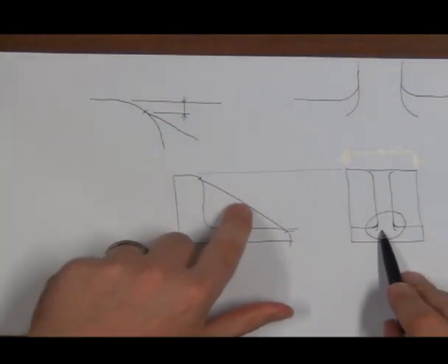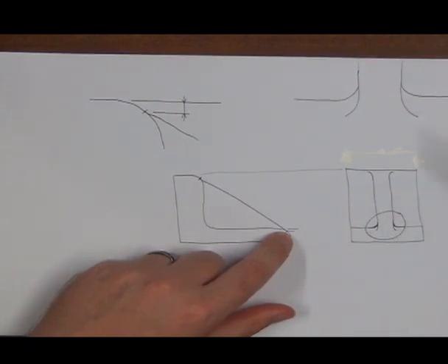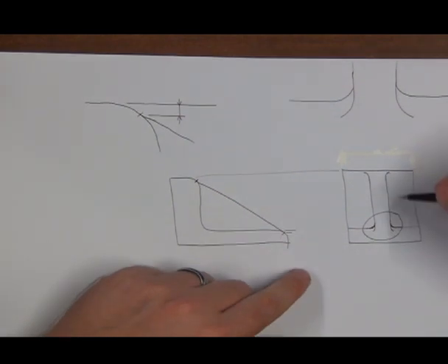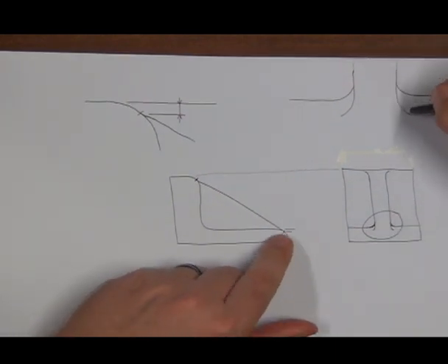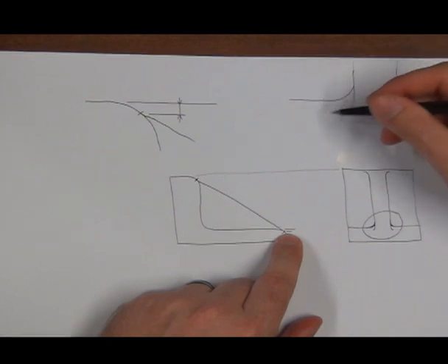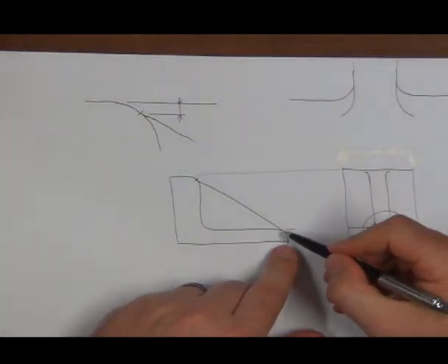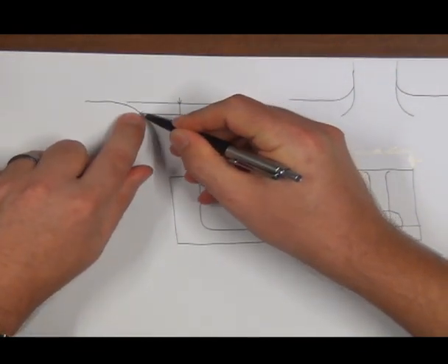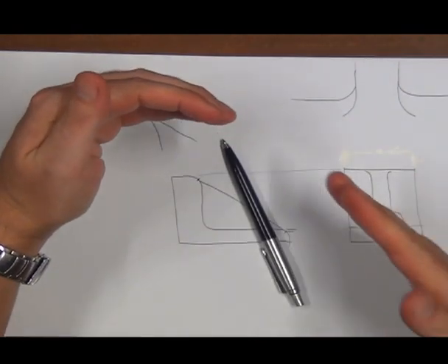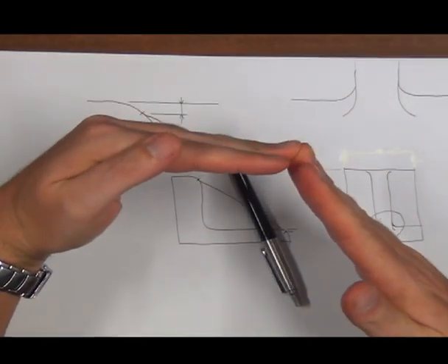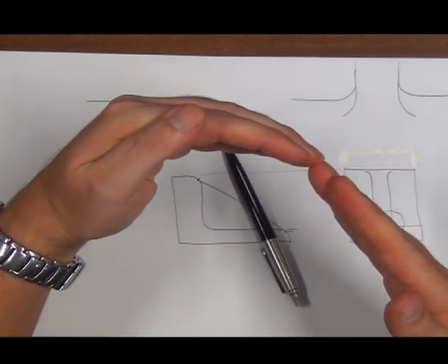So if I have a tangent line on a big radius, the way I show that it is still blending smoothly into the big radius would be to let it go slightly over the edge because of the visible height difference, and then rounding outwards to show that it blends in. There, with a tangent line on an arc, there isn't a change in plane over there. It's a nice and smooth transition from the straight to the arc. So I can't make a sharp edge there, it's a nice and smooth one.